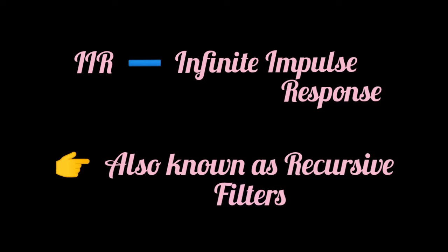It is also called a recursive filter, because the output sample is a linear contribution of some number of previous inputs and outputs. The impulse response is infinite, because there is feedback in the filter. The advantage of using these filters is they can achieve a given filtering characteristic using less memory and calculation.